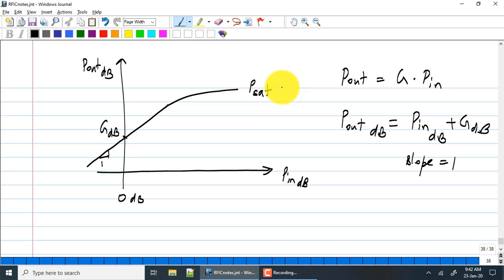Now in RF systems, Psat is very often defined for power amplifiers on the transmitter. Important for transmitters, where you are trying to squeeze out as much as possible from your power amplifier. In the case of the receiver, you will never ever be able to operate at Psat. You're already clipping so hard that at these points, you will need to start looking at signal to noise plus distortion ratio, or SNDR, not just SNR.